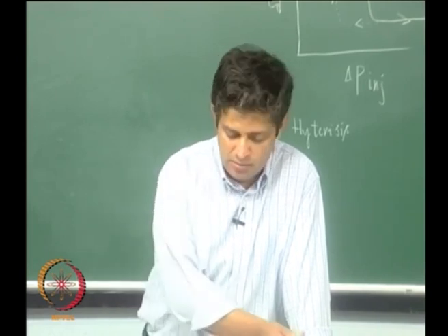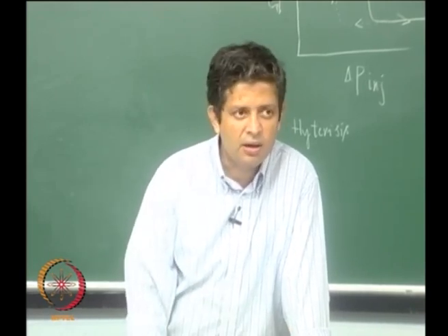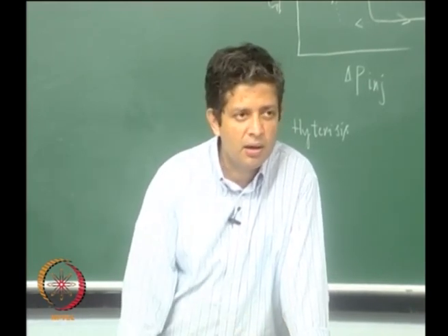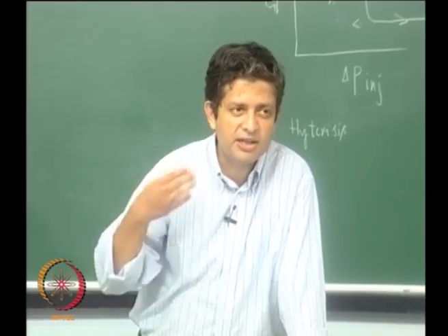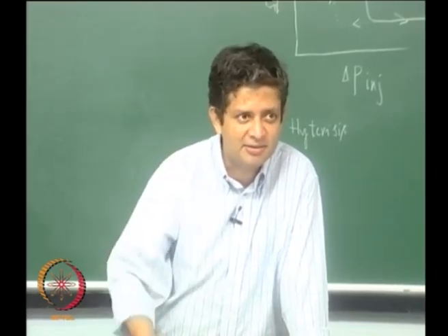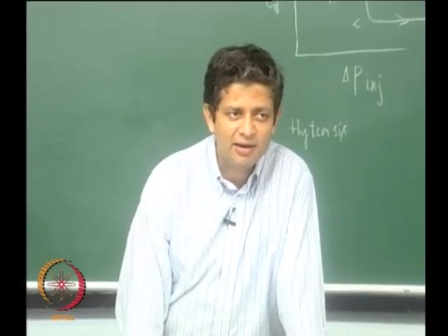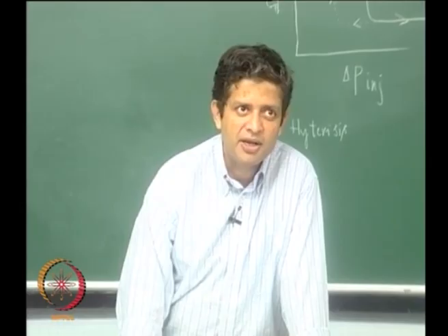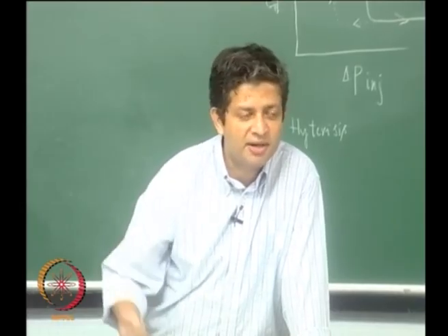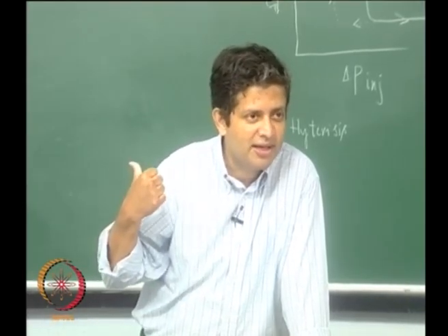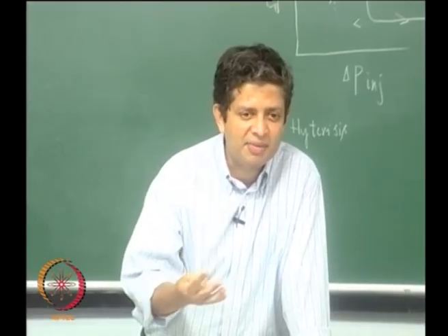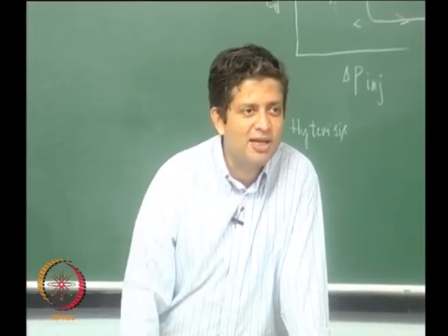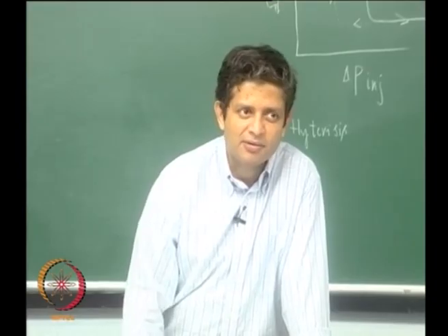You told that when the jets are interacting, they come at an angle, they diverge at an angle. They do not diverge at an angle, the resultant jet will go at an angle. So where do we exactly take the diameter of the jet? Which diameter, dj, are you talking about? dj is nothing but, we are simply assuming dj is equal to the injector diameter, okay.